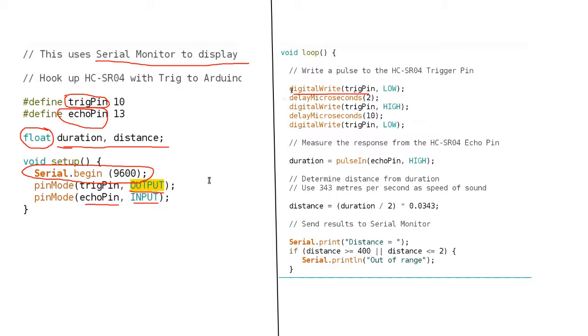And then, of course, when we now start writing, initially we set the trigger to low, and then we give it a 2-second delay. Then we send. By putting high, it means we are now sending a signal. So that trigger pin triggers the sound, then gives a delay again, waits, and then switches off. So all the time the pin keeps sending, waits for 2 seconds, stops sending, and sends again. All this will be repeated time and again.